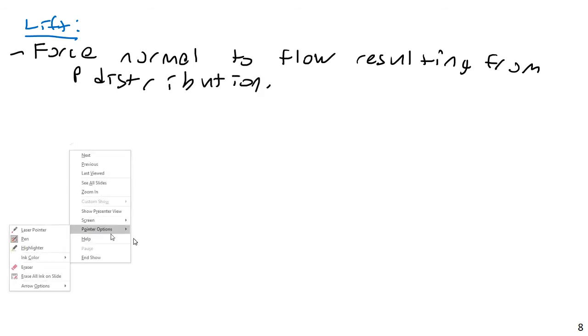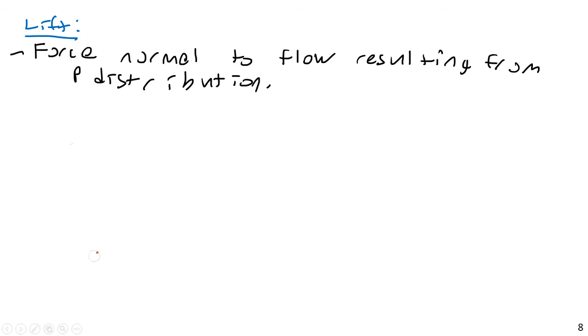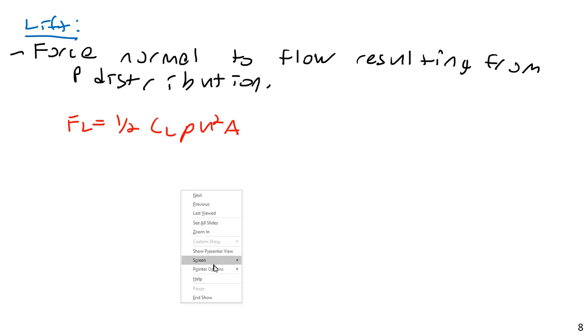So FL, the force of lift, well, the formula for this will look very similar to the drag. It is 1/2 times CL, the coefficient of lift, times rho times U squared times A, where FL is the lift force and CL is the coefficient of lift.